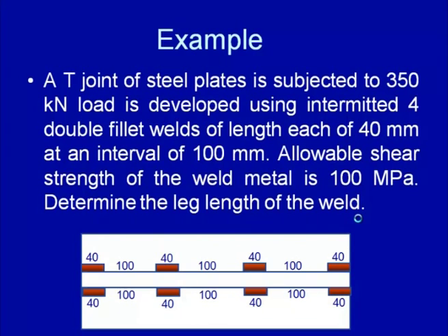In the design of weld joints, either we have to determine the throat thickness of the weld or the length of the weld in such a way that our load resisting cross sectional area can successfully sustain the external load for the given allowable stresses.